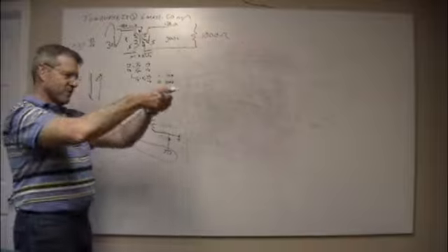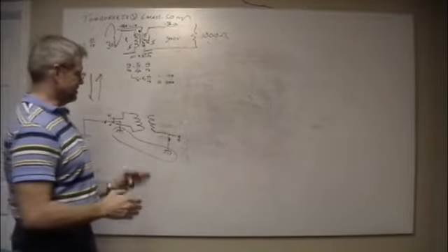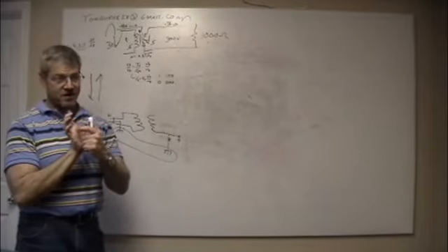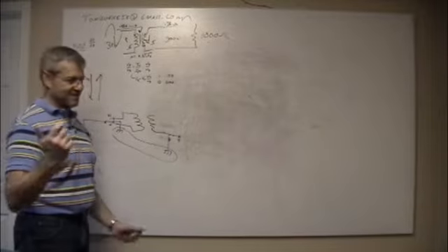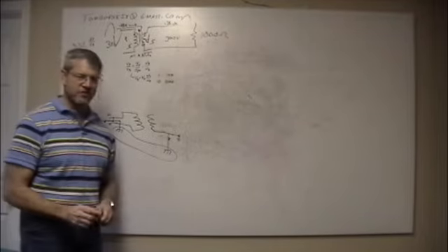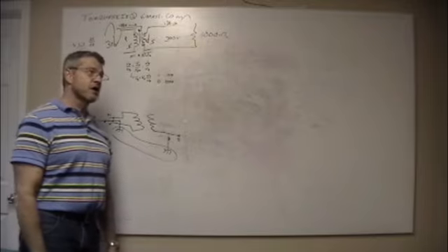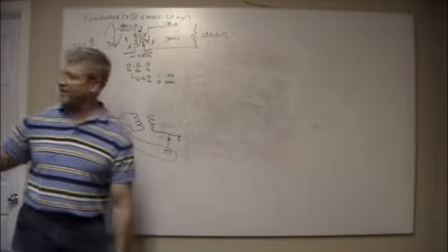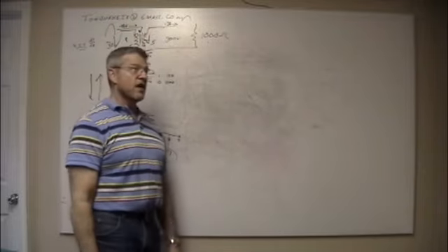But I ended up going through the house, going through different outlets. Oh, yeah, that one's 110. So it was a high resistive connection is what it was. And when I pulled the breaker out, it had little arc marks on it. And so I bent everything back into shape and plugged it back in, and everything was fine. And it was weird. I had the longest time troubleshooting this because I troubleshot it for over a year. Because, okay, there's something going on. Dad, our lights aren't working. All right, well, I'd flip the breaker, this breaker. They're still not working. All right, come over here, flip, they're still not working. I come over here and flip one that was completely unrelated. And everything, they're working.